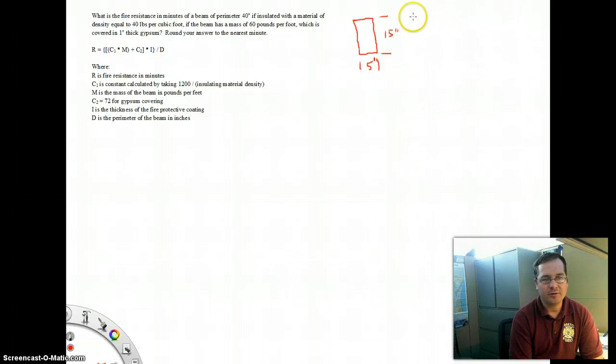Another more typical configuration might be a wide flange beam. You'll hear these called I-beams, which they really are not. The correct term is wide flange. I-beam is a beam that looks similar, but was an older technology. So pretty much wide flange beams are universal in construction now.